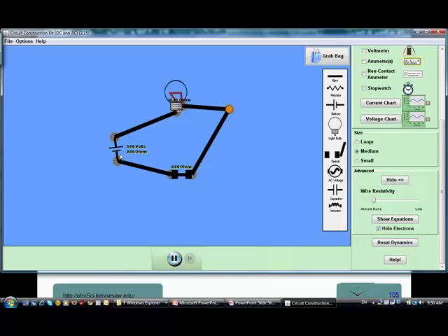Two bars, very much like a capacitor, except one of them is smaller than the other. The smaller one is the negative lead, the larger one is the positive lead. Remember, this is very much like a minus sign and a plus sign. You need to use more ink on the plus sign, so you need to use more ink on the positive lead. Now, wire is just a connection.